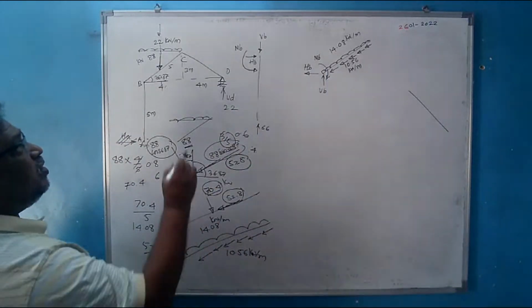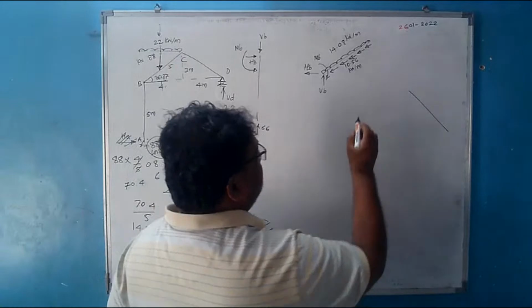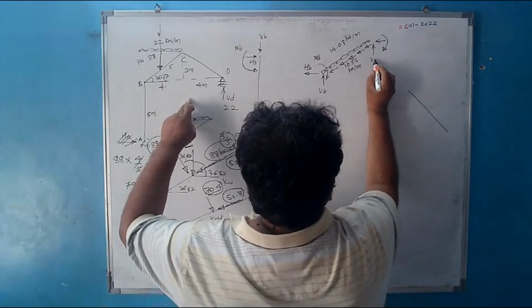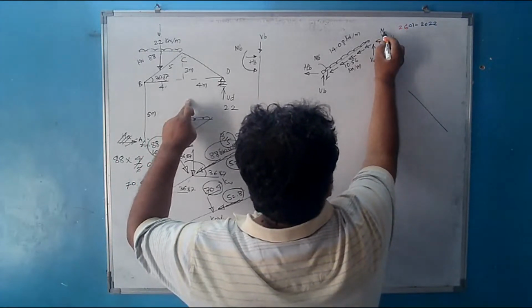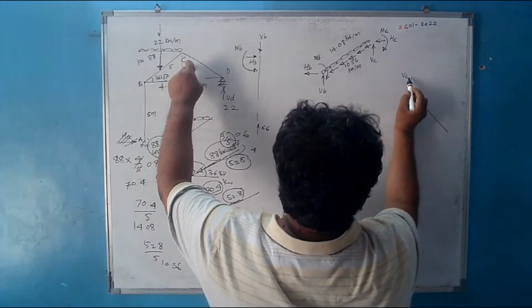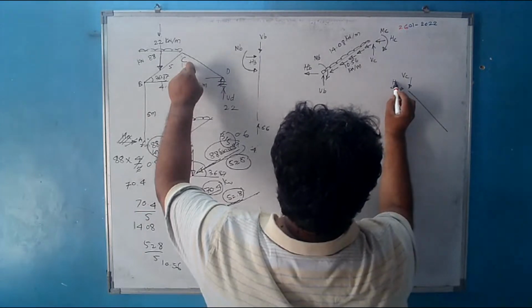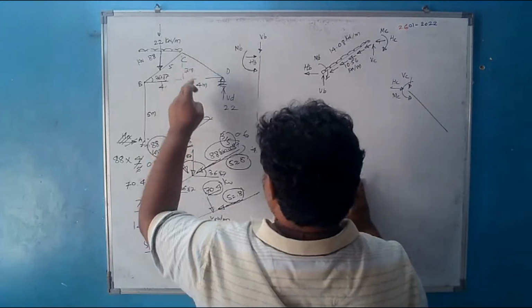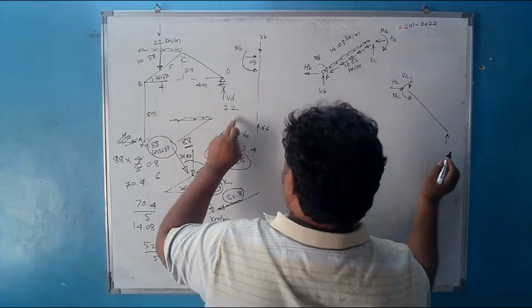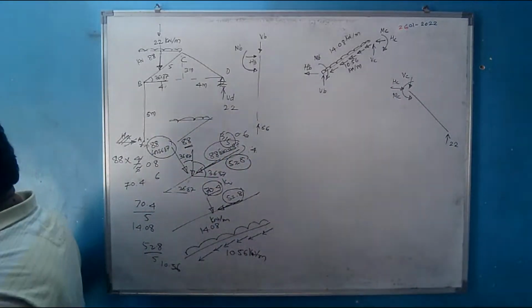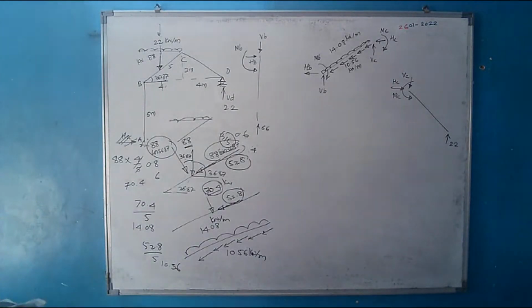That is this. Now at this joint C you resolve a vertical, a horizontal and a couple. This is vertical at C, horizontal at C, and this is the moment at C. Now whatever I have considered here, I will consider in the opposite direction. HC, and it was clockwise, so here it must be anti-clockwise MC. Now this VD is vertical here, and that is equal to 22 kilonewton. That's all finished. This is how the diagrams are sketched.